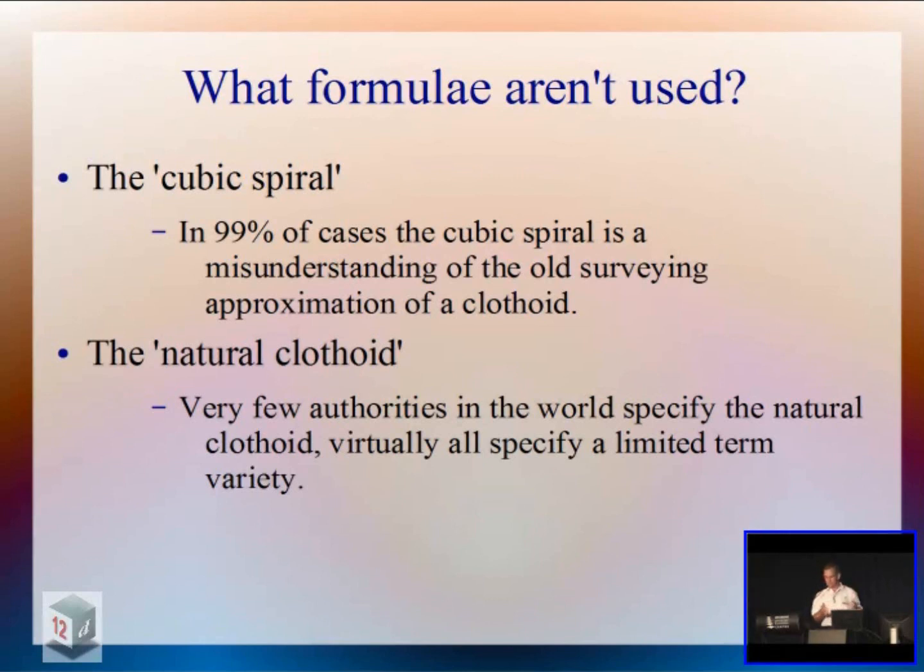It expanded to 4 or 5 turns. It is not the natural clothoid. It is a completely different curve. The clothoid, again, is a very good approximation for the first, from a straight into, say, 15, 45 degrees, but after that, it spirals off into the distance. It's not a true spiral.